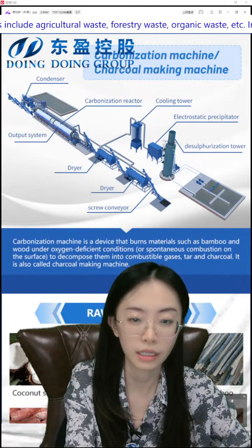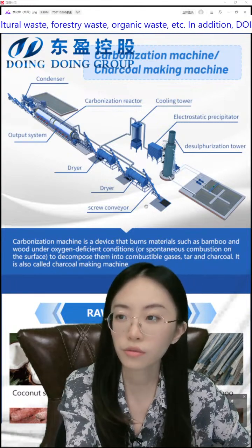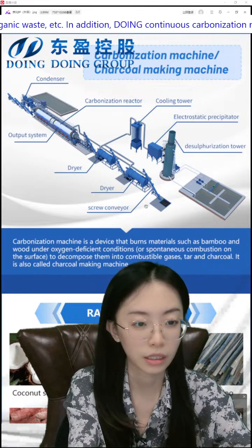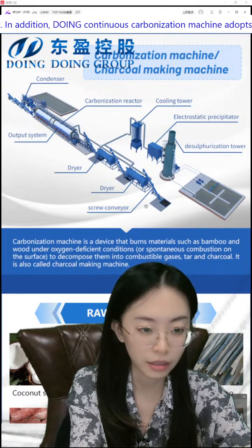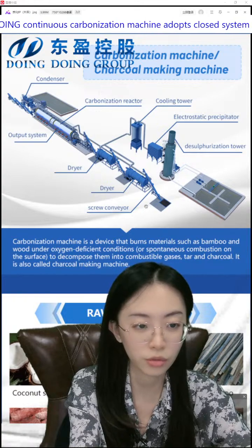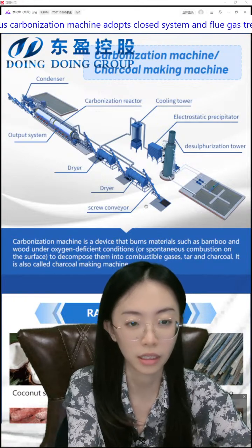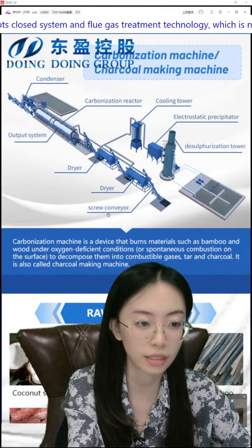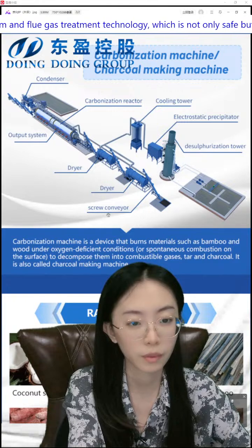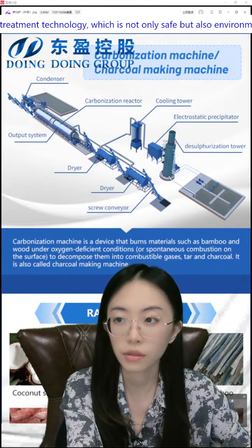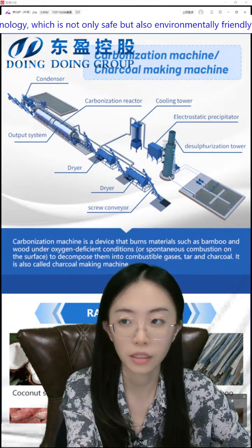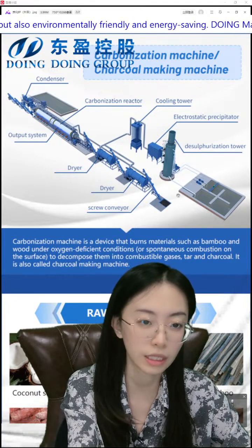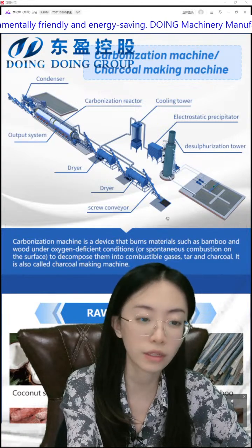This is the first step. Then we use a screw conveyor, or a belt conveyor which has many dividers on it, to feed the raw materials into the dryer machine. If you use the screw conveyor, a screw puts the raw materials in. You can also use a forklift to feed it into a hopper, and then into the dryer. This is the feeding step.